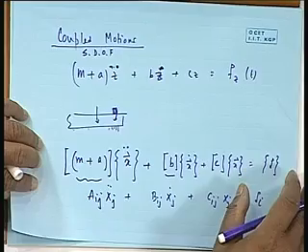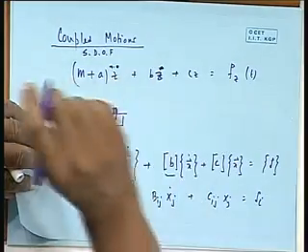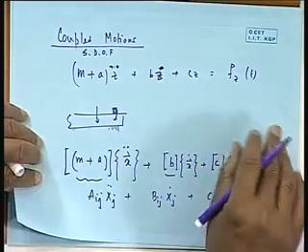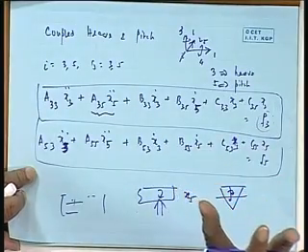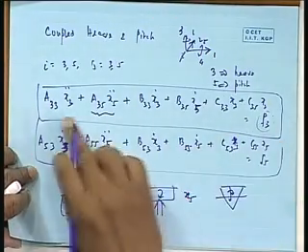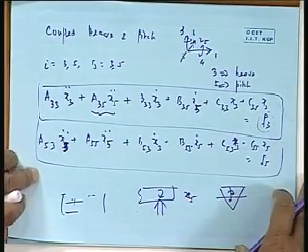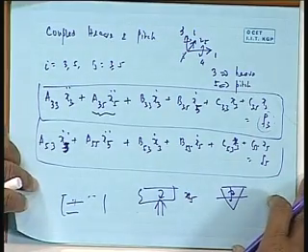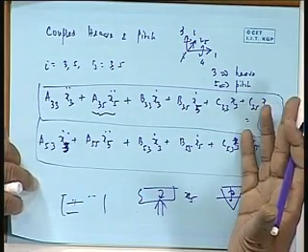But in a ship it turns out that is not always true. You can break it down to three parts, but you cannot have only heave. Heave and pitch and surge. Surge is not normally common, so heave and pitch is the most common coupling that is always taken, and this is very important. Therefore, you usually cannot solve a problem with only heave, but you have to have heave and pitch together.